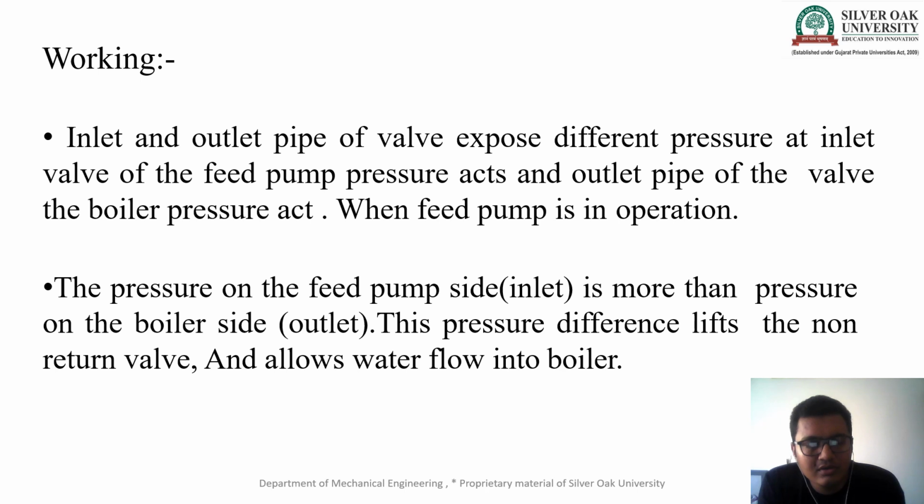Now, the simple working of the feed check valve: the inlet and outlet pipes of the valve are exposed to different pressures. At the inlet is the feed pump pressure, and at the outlet pipe of the valve is the boiler pressure.